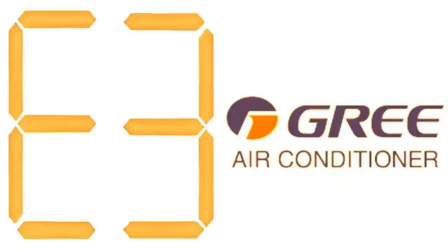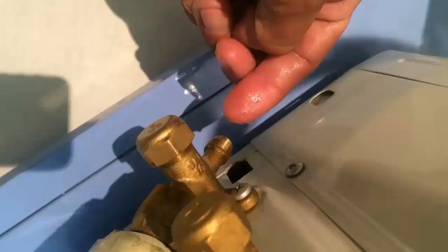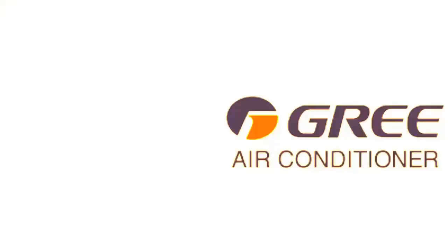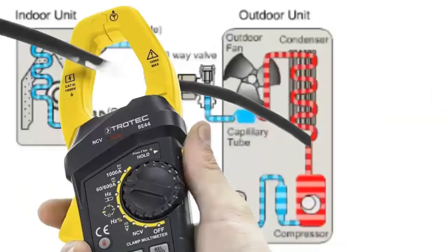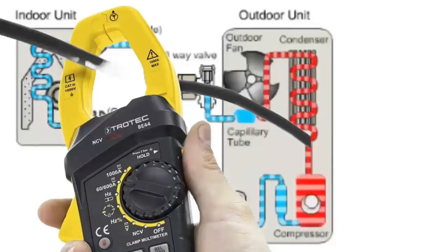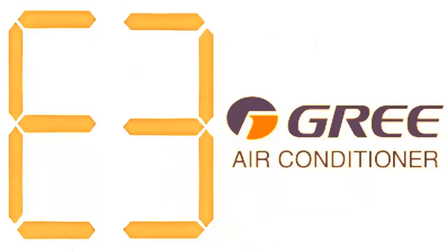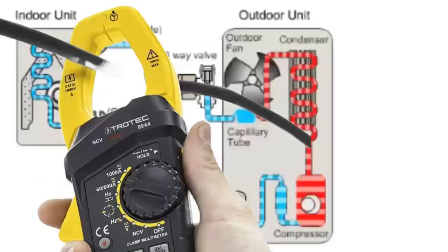A. It is essential to inspect the system for leaks. Check for oil stains, which may indicate refrigerant leaks. B. Use a clamp meter to measure current consumption, as refrigerant leaks often result in lower than normal consumption. Additionally, electrical issues in the compressor can cause significantly higher consumption than usual.